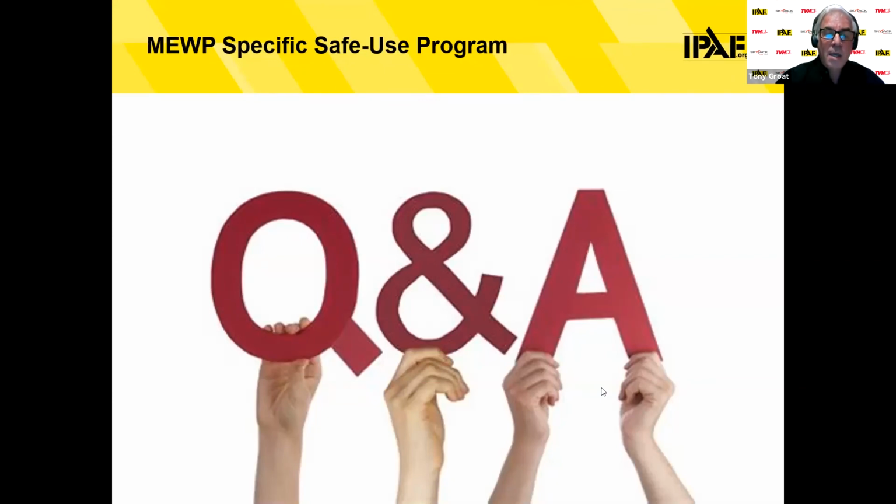And are they making any updates for fall protection requirements on scissor lifts? Well, the answer there is the standards are drafted. There are no new requirements in either the Canadian or the US ANSI standards. The requirements basically are that you are required to be wearing personal fall protection when you're on a boom type lift, so it's a group B machine. You're required to be wearing it at all times. And when you're on a scissor lift or a vertical type lift, a group A machine, you're not specifically required to wear it unless a risk assessment identifies a cause for you to be wearing it.